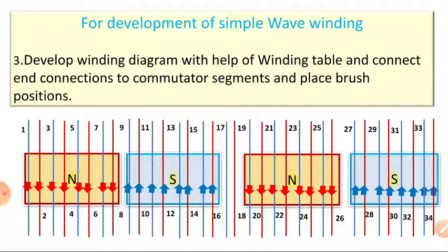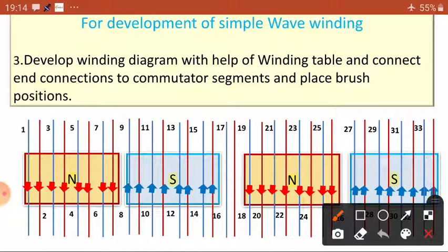Now I am going to connect the first conductor to here. You can see this first conductor, I am going to connect to the 10th conductor. Okay, this is the 10th conductor. The 10th is connected to the back of the table, where I am going to the 19th conductor. Where is the 19th? So this is the 19th conductor, the blue color. This next 19th conductor is connected to the 28.